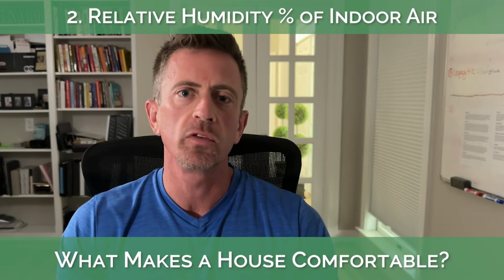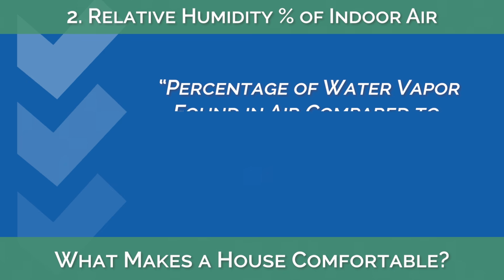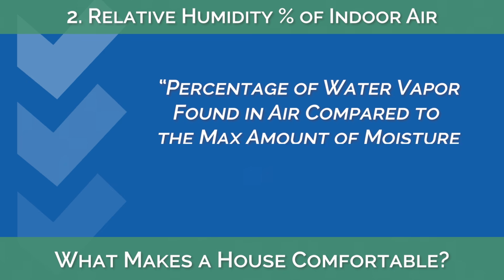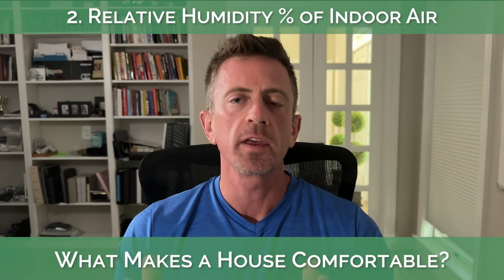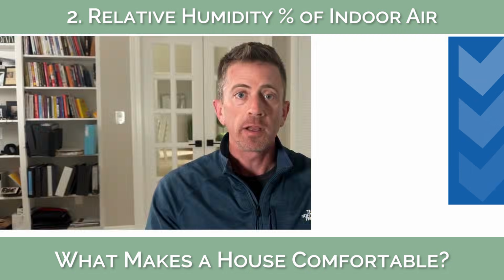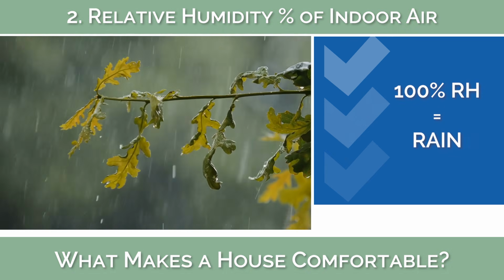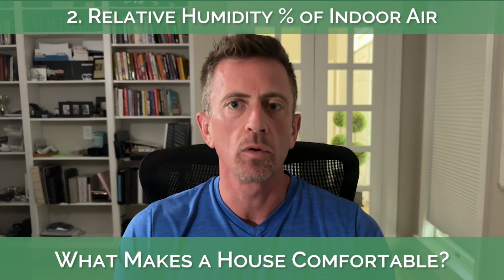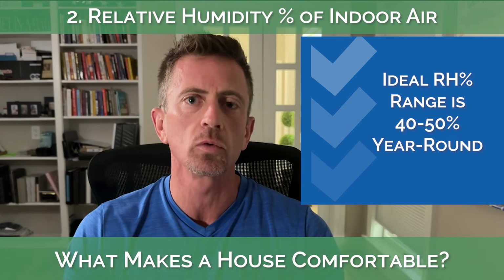Number 2, relative humidity of indoor air. This is the percentage of water vapor found in the air compared to the maximum amount possible at that same air temperature. Think of it this way. If the relative humidity of outdoor air is 100%, then it will be raining outside. The air can't hold any more moisture and it has to release it. Inside your home, the ideal relative humidity range is between 40 to 50% year-round.